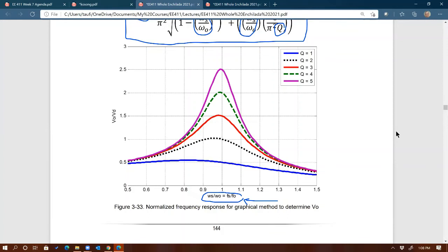Different core sometimes, different ways of connecting the wires, right? Yeah, different materials of the cores. So high frequency transformers are basically what you want to use for this type of application. And also depending on the power, right? You will have to look not only for the frequency range of the transformer, but also the wattage rating of the transformer. Right. So make sure. Yeah, I'll definitely keep that in mind.